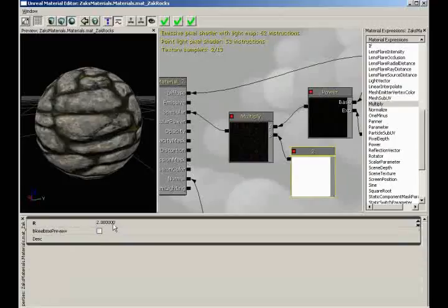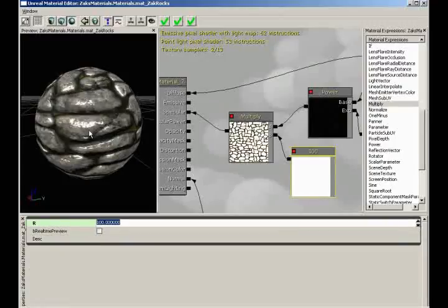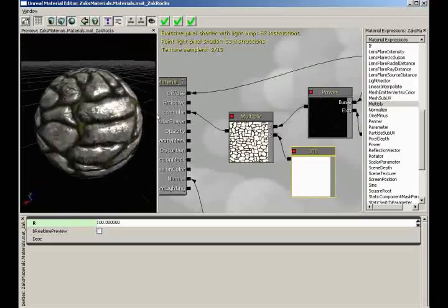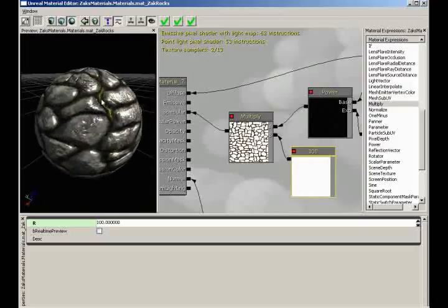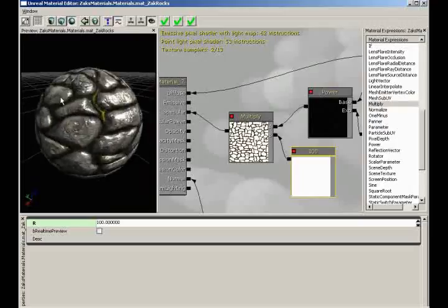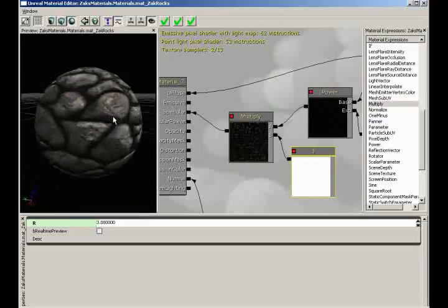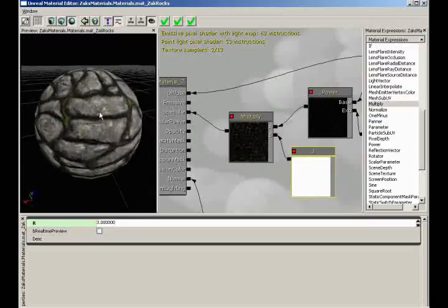If you don't believe me, take your constant value and drive it to something nuts, like 100. Now our rocks are almost sparkly, like they're some sort of metal. But take a look at our mossy areas. They're nowhere near as shiny. In this particular case, I've overblown it. I've really overdone it, so you'd really want to keep this to a lower value. Let's say 3, and you can start to see some shine there, and our moss doesn't look shiny at all.